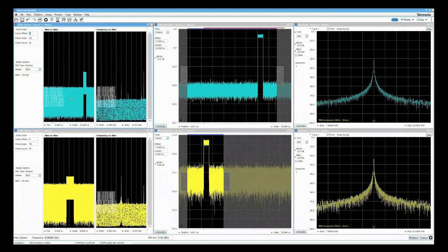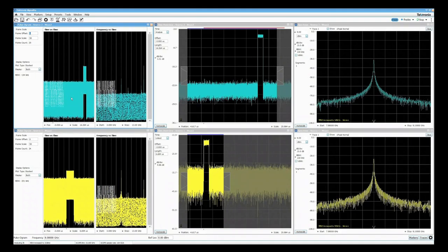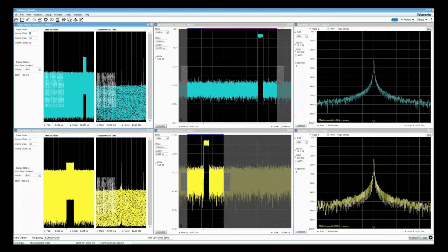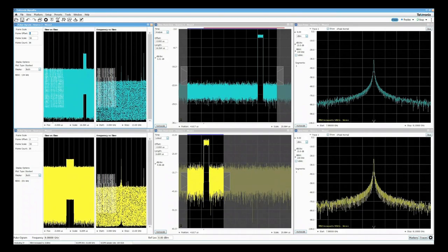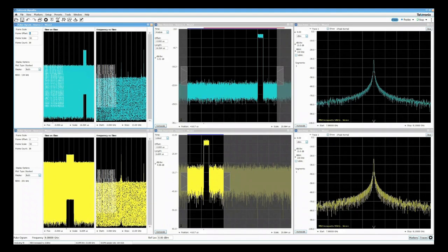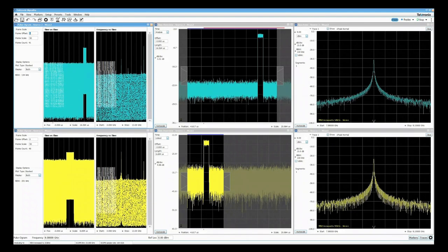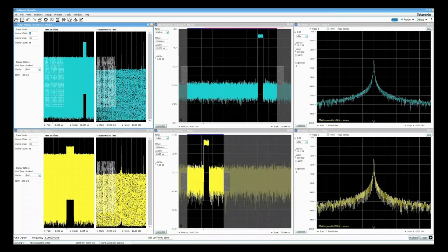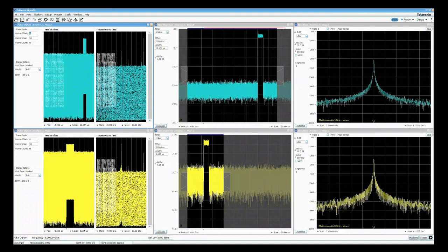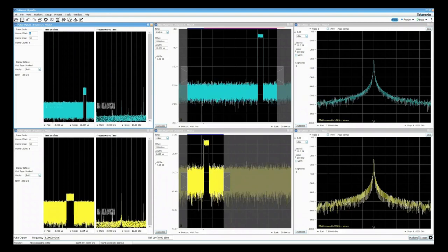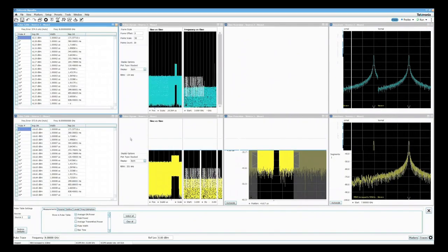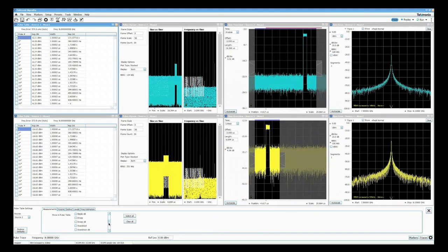The combination of automatic pulse measurements and fast frame segmented memory capture, along with independent controls, allows us to analyze intricate scenarios such as MIMO radar. The pulse analysis can be executed concurrently across multiple channels. The advanced pulse analysis package offers up to 31 measurements to automatically characterize the pulse sequences.